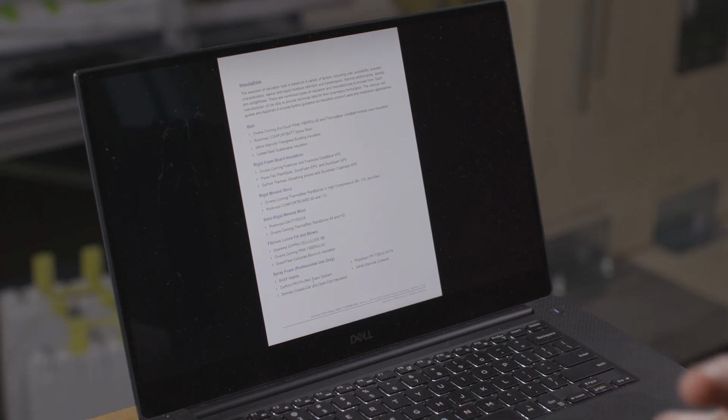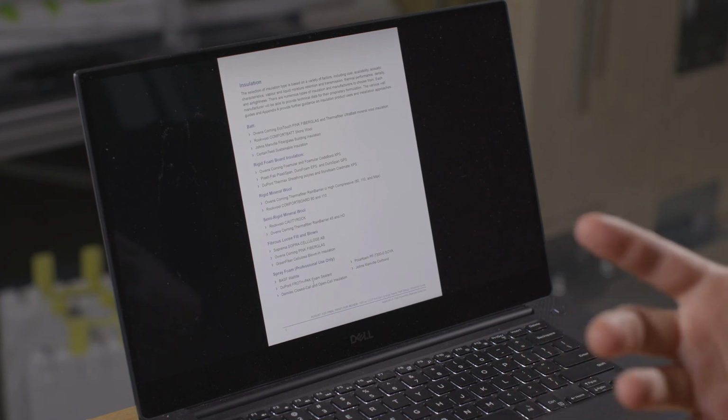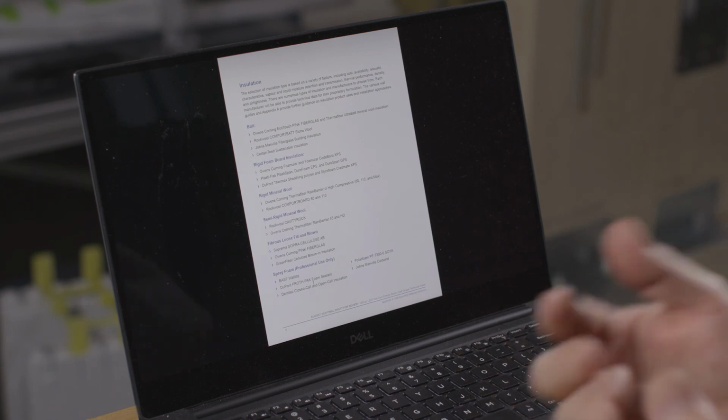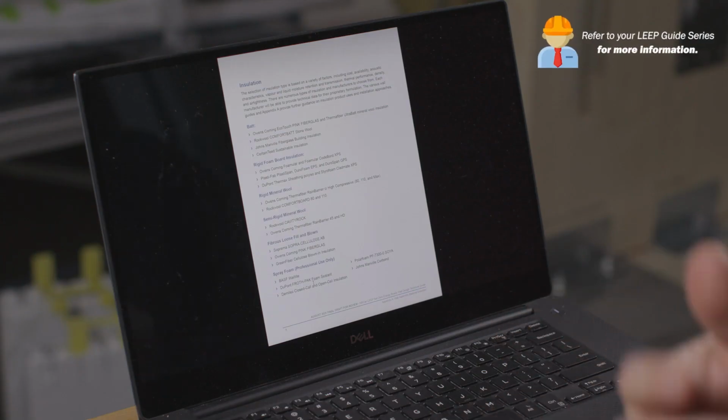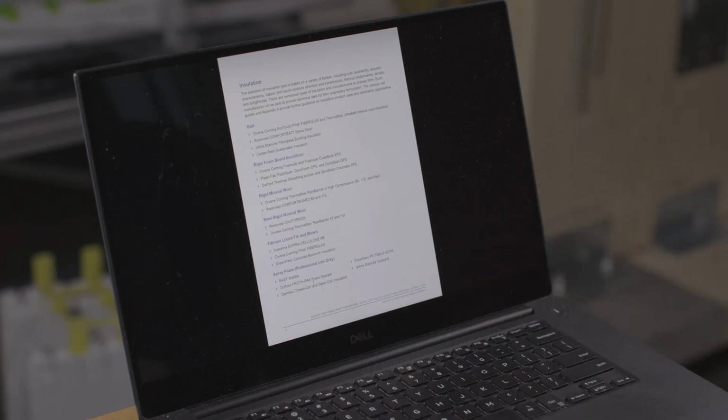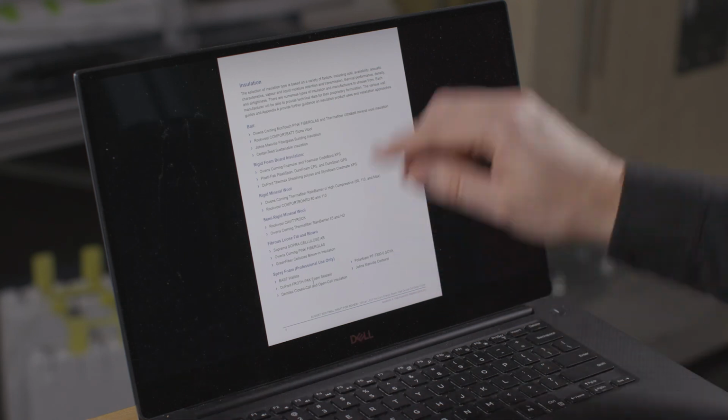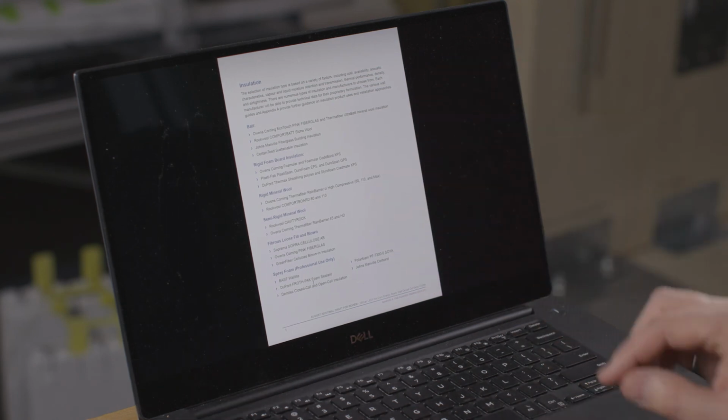Insulation. In the other videos, we talked about the different types of insulation. So we've got batts, we've got rigid boards, and in the rigid boards, we've got XPS, EPS, rigid mineral wool, and semi-rigid mineral wool, which is a softer density than the rigid. We've got fibrous loose blown, so things like cellulose and blown-in fiberglass. And then we have spray foam. Spray foam is typically installed by professionals. These are usually 2-component spray foams, closed cell or open cell spray foams. And so again, some starting points there for suppliers in Canada that can help you out.